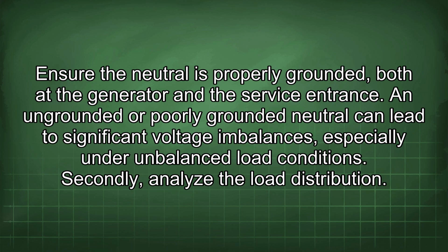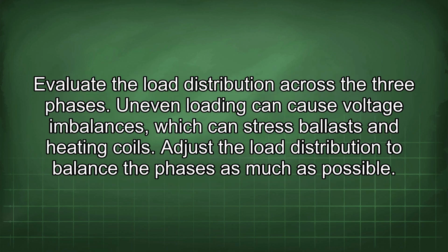Secondly, analyze the load distribution. Evaluate the load distribution across the 3 phases. Uneven loading could cause voltage imbalances, which can stress ballasts and heating coils. Adjust the load distribution to balance the phases as much as possible.